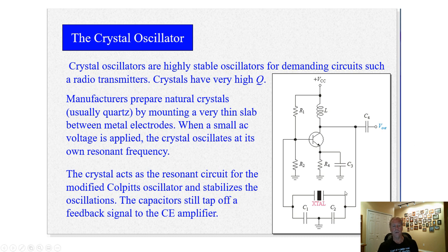All right. So here's a modified Colpitts oscillator where we've replaced the inductor with a crystal. Again, we use another common emitter transistor amplifier and just feed its output back to the input through this resonant circuit formed with this crystal. Again, you could build this circuit with a 3904 transistor, and you bias it correctly using this resistor divider. It would work. This is a very common circuit, and you could run this in the megahertz. It would work great. This is a very good solid oscillator circuit.